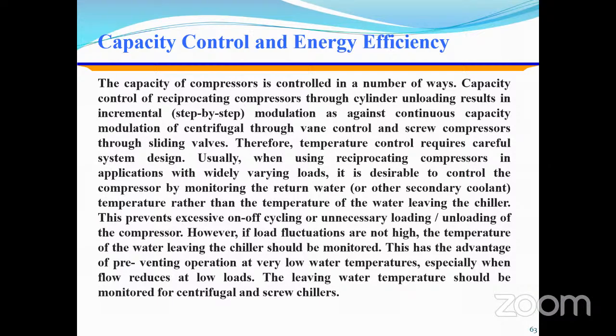However, if load fluctuations are not high, the temperature of the water leaving the chiller should be monitored. This has the advantage of preventing operation at very low water temperatures, especially when flow reduces at low loads. The leaving water temperature should be monitored for centrifugal and screw chillers.